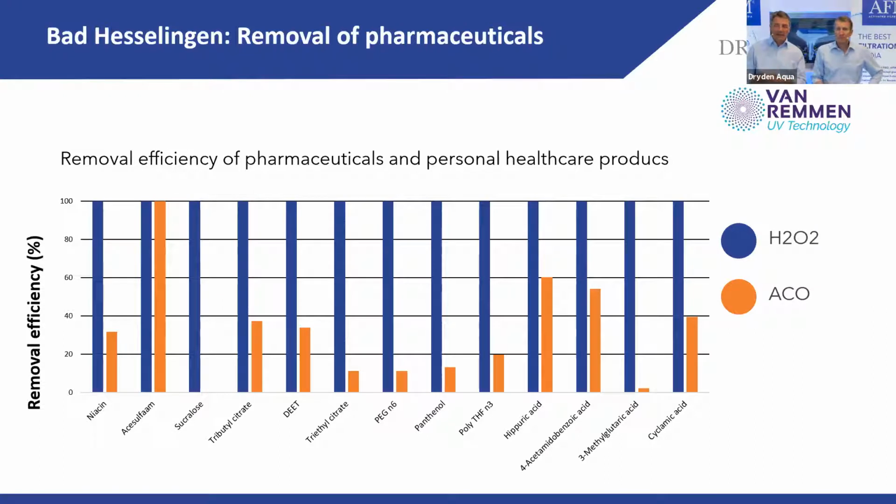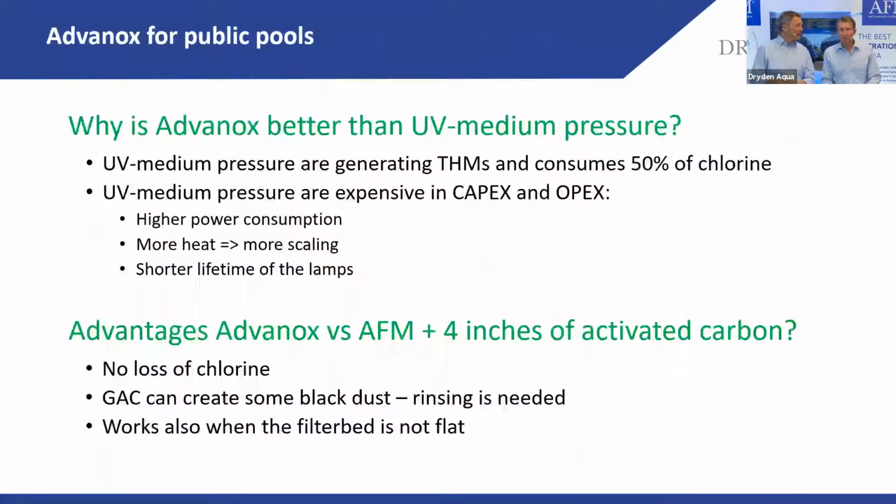We have seen it, as I said, in water treatment with benzidine, and benzidine is one of the most difficult chemicals to break down. So this you get on top. This is why you use advanced oxidation today in wastewater, especially industrial wastewater. And they all do it the same way, always high dose UV, low pressure, 5,000 joules, and then peroxide.